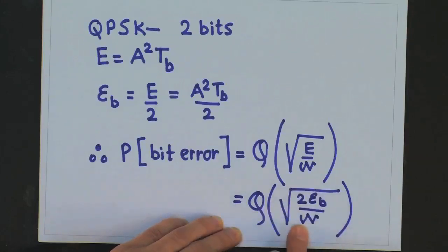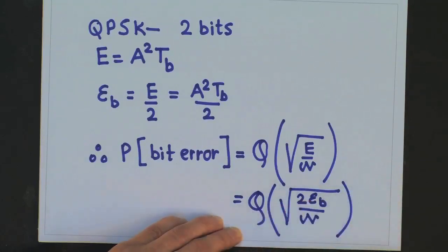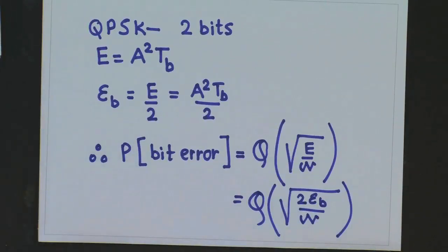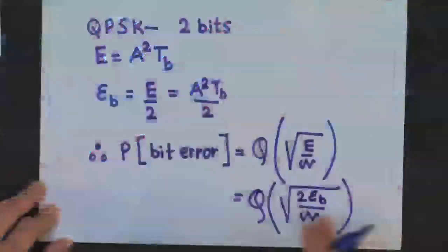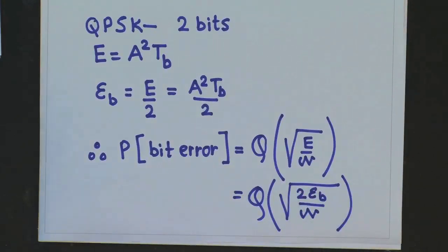With QPSK modulation, the bit rate can be doubled without requiring any additional bandwidth or sacrificing the error performance. Interpreted differently, to deliver the same transmission rate at the same bit error performance, using QPSK reduces the transmission bandwidth to half of that required by BPSK. Now, we will look at the alternative implementation of the QPSK modulation, and we will do this with the help of an example.